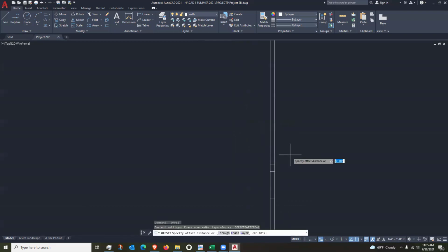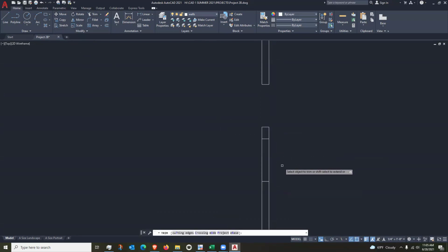The other door is 36. And then I'll just do some trimming and I can click this and this. Oh, by the way, this is kind of cool. What I can do here is, remember that if I left click, I can trim both of these lines at once.